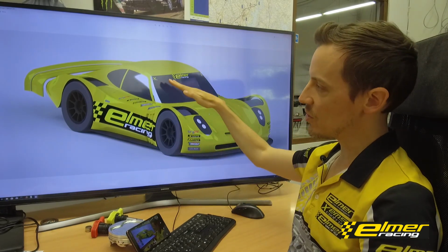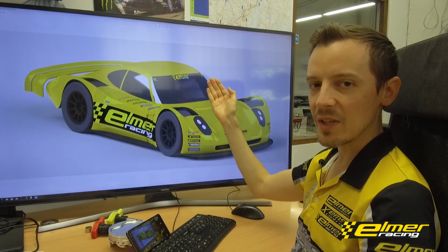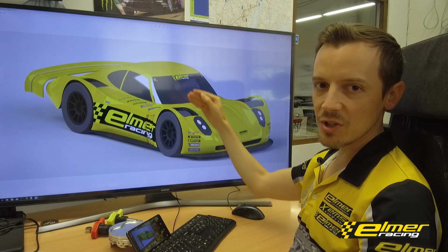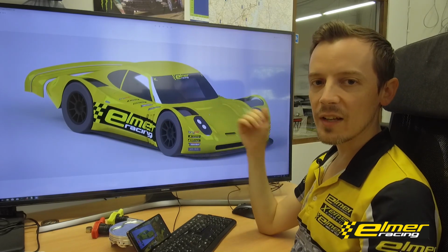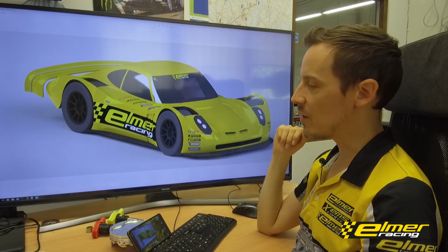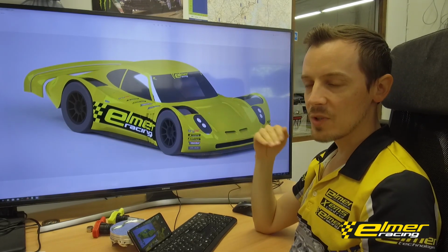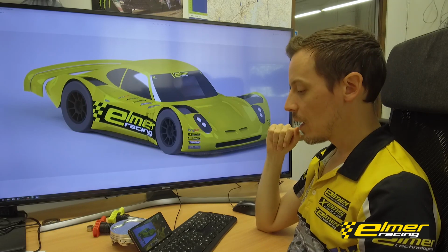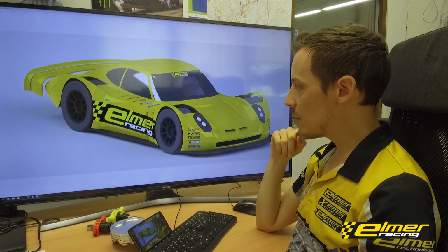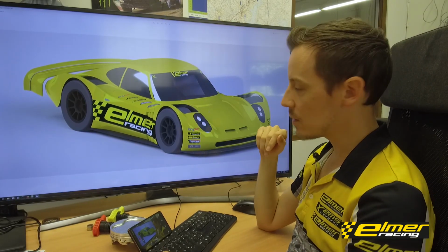If you keep the pressure on top of the car the same, or possibly even increase it, you'll have a much higher pressure differential, and you can create lots of downforce very efficiently, both aerodynamically and design-wise. But yeah, let's go look at some of the things that people copy.